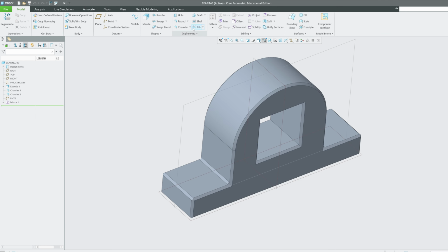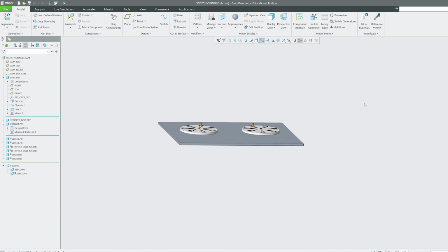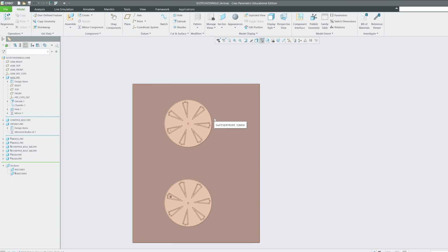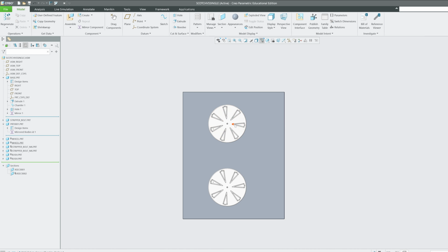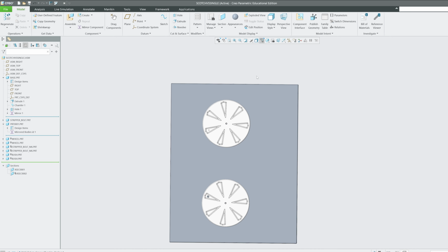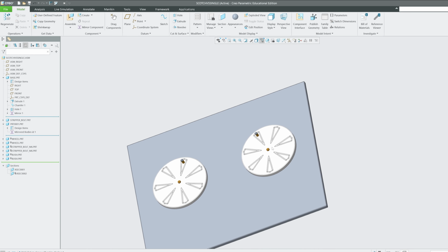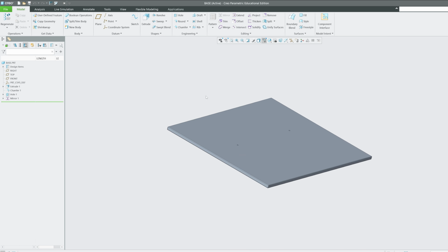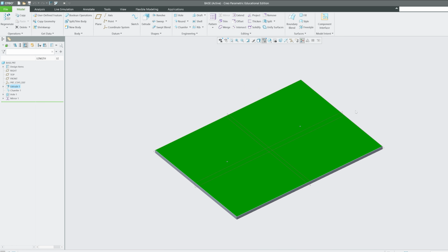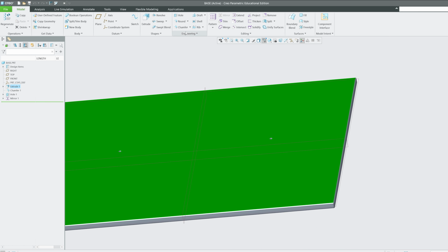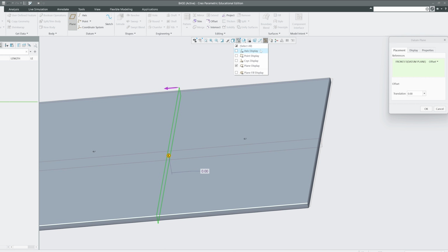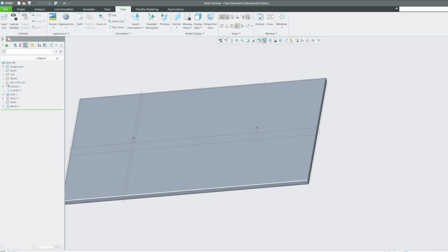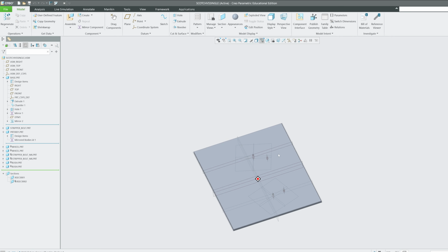Alright, now let's save and close. Okay, so it needs to be like this plate, and now I'm gonna add the bearing. It needs to be exactly in the center, and for that either I can calculate the center, or even better, I can create a plane in this plate, enable plane display. So this kind of gives me, I would say, better freedom. I'm gonna make it parallel, and then let's also mirror it. Click on view, close. Yeah, so this now is going to give me freedom.